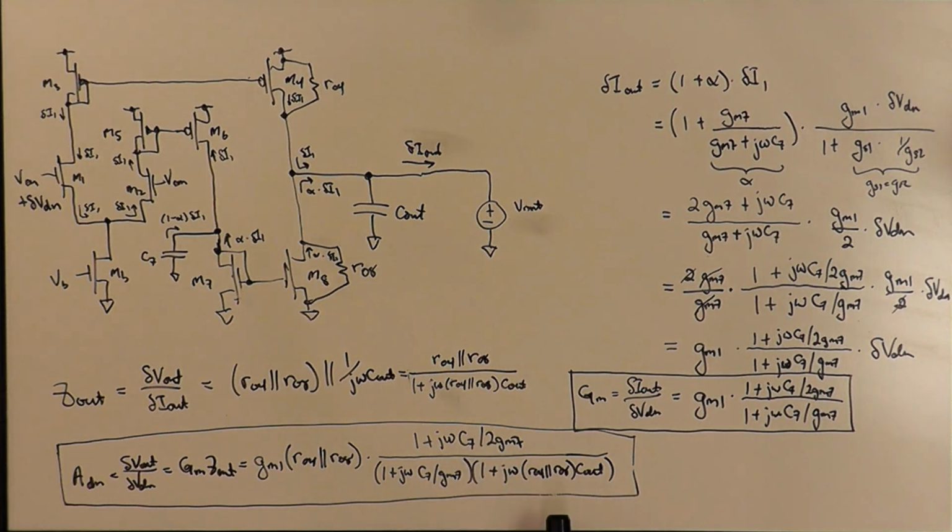Okay, and in point of fact, that basically means that this capacitor sort of affects the behavior, the frequency response of the circuit at a much higher frequency than this capacitor does. And often we're interested in what's called the dominant pole, which is the pole that kicks in at the lowest frequency. And it's really that pole that determines the dynamics of the circuit and the stability of the circuit. And if we're interested in any of the other poles, we're interested in where is the first non-dominant pole relative to the dominant pole.